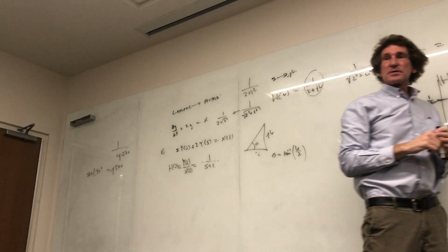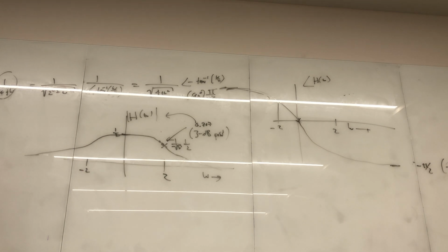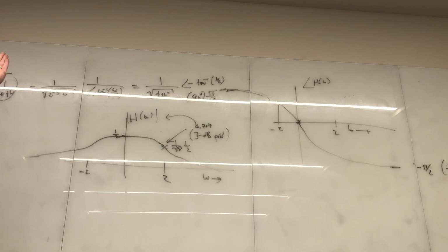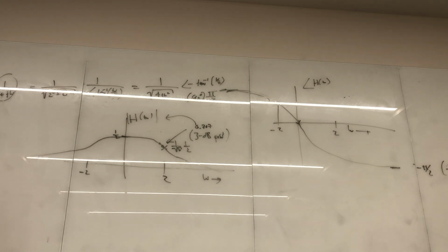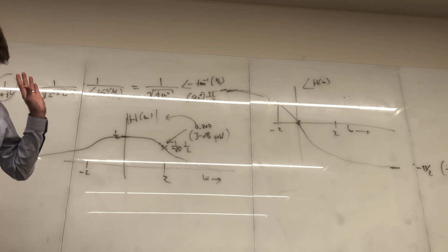Now please make sure you see this. You'll be asked for magnitude and phase plots of simple functions. And believe it or not, a lot of people are not used to doing this. When I taught circuits, I didn't force this issue on people. I may have mentioned it in passing, but you have to be aware of this. In your laboratory work, do you have to do magnitude phase plots? Not yet. Have you had your circuits lab? Okay, well, you're going to get them in some lab, and I don't know which one it is, unfortunately, but you have to be aware of this. This is very important to be able to do. Do you all understand what I've done? This is just common for any kind of analysis of a system. You look in the frequency domain, you see the transfer function's properties, how it behaves, magnitude and phase.